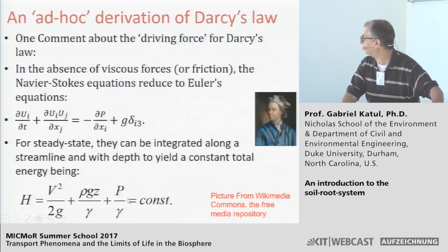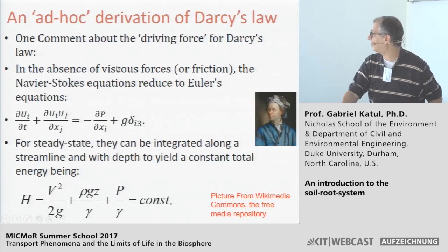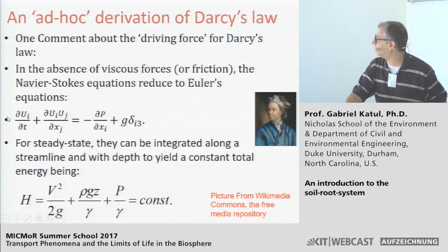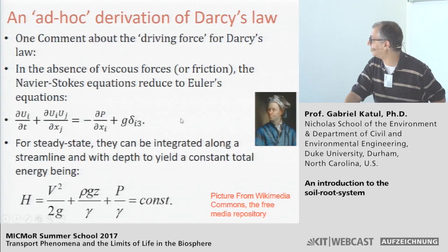Okay. Now, another comment that I would like to mention, and this actually highlights the tension between hydrodynamics and hydraulics. If you take the Navier-Stokes equations, as Euler has done, and you throw away the viscous term, and then you depth average this equation for steady state conditions, you could actually show that for this system, the total energy will be conserved.